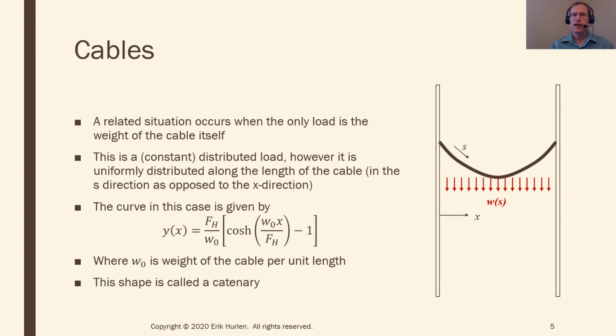A related situation to that is something that happens quite often, and that's if the weight or the loading function is directed along the length of the cable. So as opposed to the x direction, the previous parabola was uniform in the X direction. But if you think of something like the cable itself has weight, and that weight is not directed along the X direction, it's directed along the length of the cable itself.